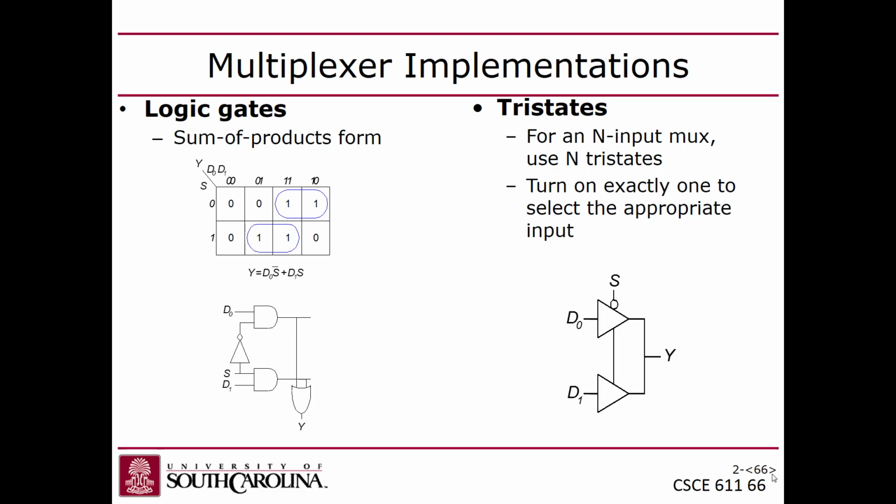I'm using this term here. This is a fan out, where you have one wire that's connected to multiple inputs. That's a fan out. And a fan in is when you have multiple wires that you want to reduce down to one wire. So you have to do that with a gate or a multiplexer. You can't just connect multiple outputs to one, but you can do it through a gate. So this is a fan in. You guys with me?